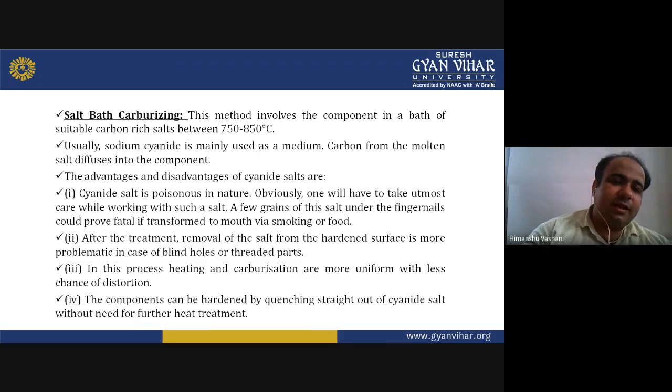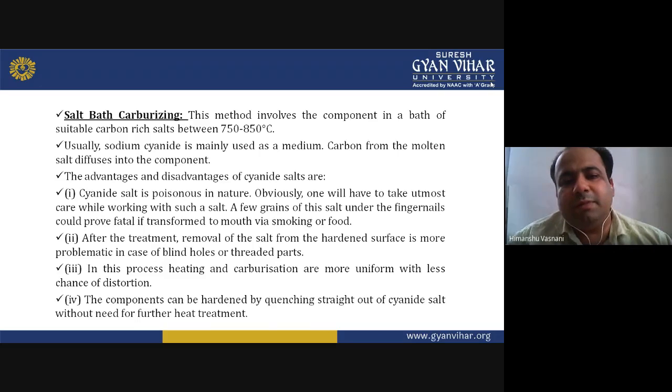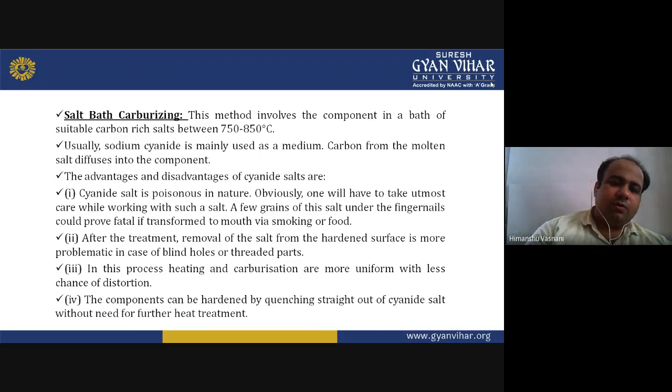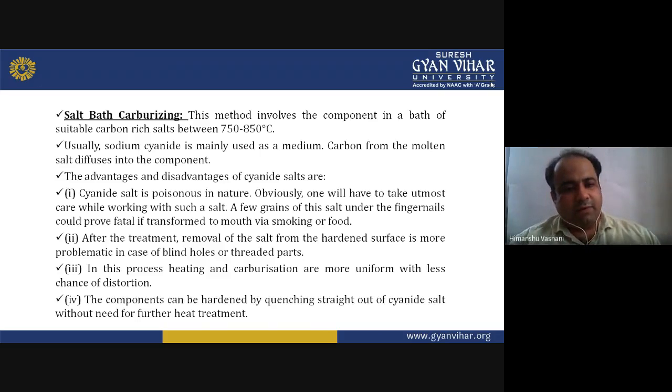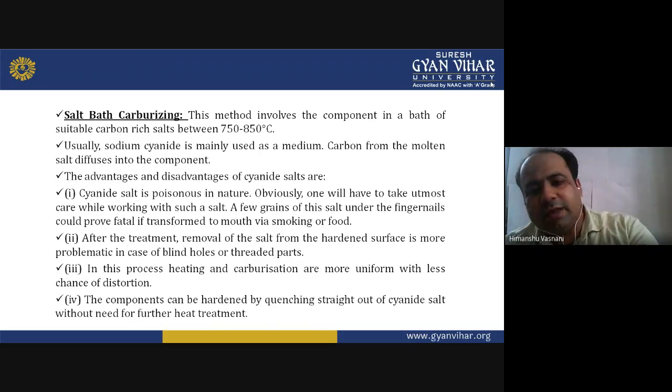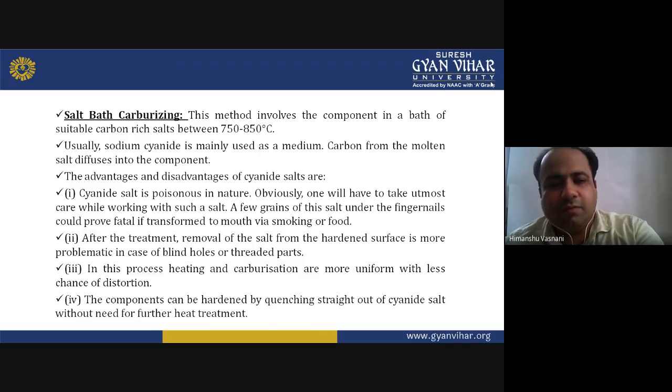In this process, heating and carburization are more uniform with less chance of distortion. The components can be hardened by quenching straight out of cyanide salts without the need for further heat treatment.